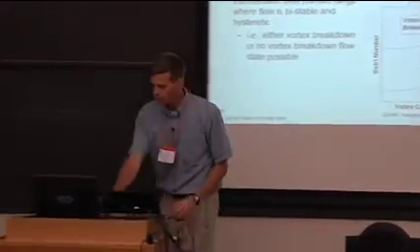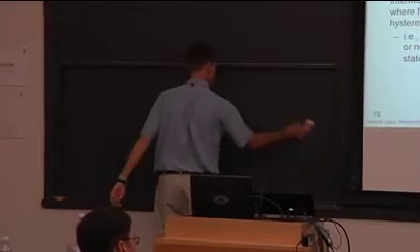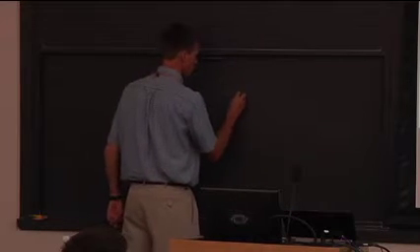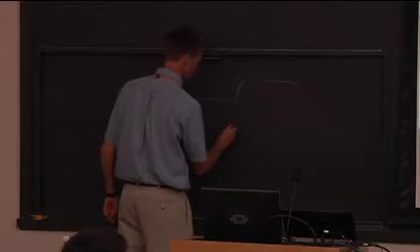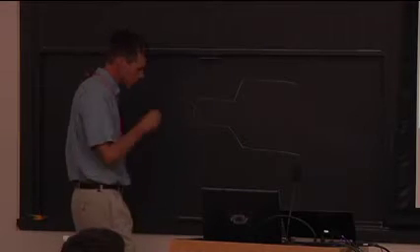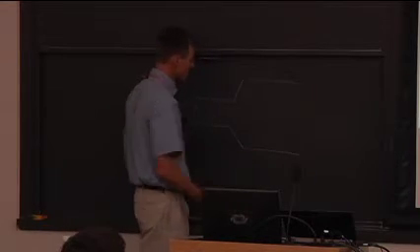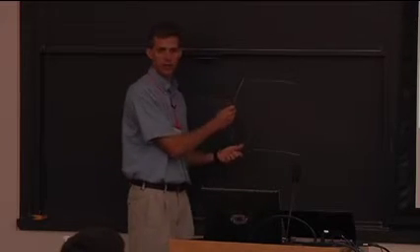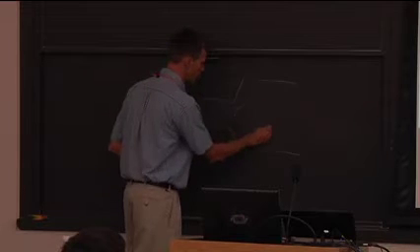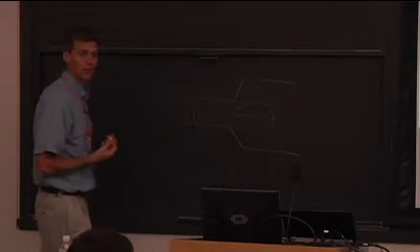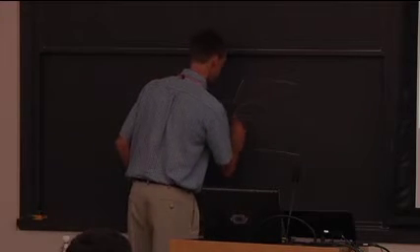So what does that mean? Let's think back about a very typical design for a gas turbine combustor, which might look something like this, where I have this swirling premix flow here, and what happens is that this rapid expansion is a huge adverse pressure gradient, and so it'll force vortex breakdown. The flow will break down right about here, and you get this nice recirculating flow pattern, and that recirculation pattern stabilizes the flame. And so nominally, you'll have a flame that might sit somewhere out here like that.